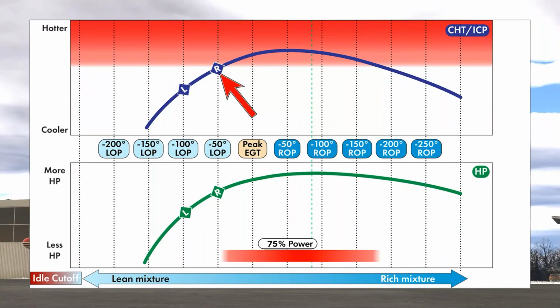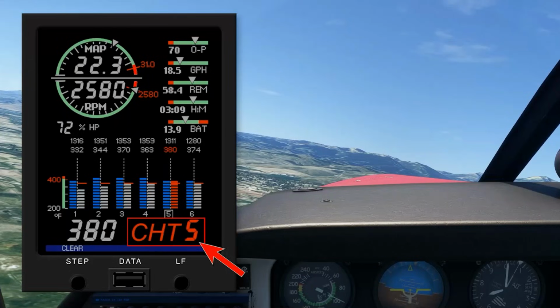And so as you're doing this, the thing really to look at is CHT. In most cases, CHT is a pretty good proxy. And if you can keep CHTs at reasonable levels, more on what reasonable levels mean later, then you can have a little more confidence of dipping your toe into the red box a little bit more. Whereas if CHT is high, you may err even farther away from where the red box is in principle.